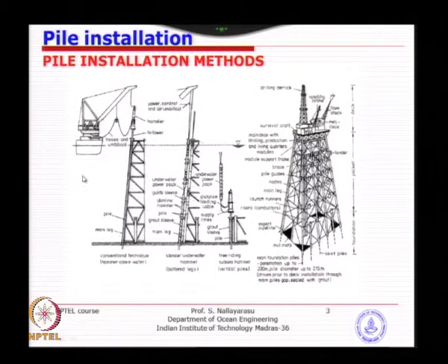So, this main pile installation, once you have one of the piles inserted and driven to that level, almost 2 meters or so slightly above the jacket level, then you remove the hammer, the hammer will be taken back to the barge, bring the second pile section, put it on top of it and do the welding. Now imagine how it can be done.